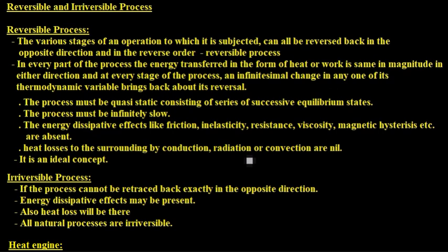Another important condition is that energy dissipative effects like friction, inelasticity, resistance, viscosity, magnetic hysteresis, etc. are absent. Also the heat losses to the surroundings by conduction, convection, radiation, etc. are absent. Then only is the process reversible.